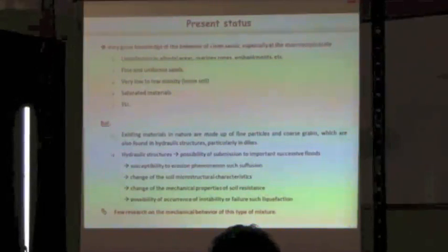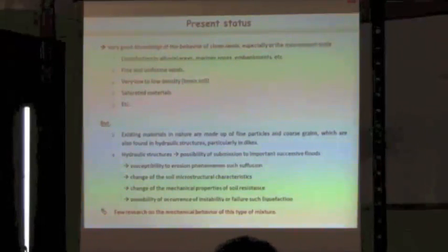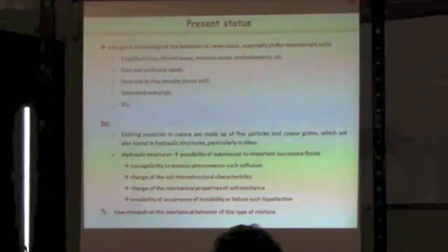particularly in dikes. Why did I introduce hydraulic structures? It is because such structures are often submitted to important successive floods, which could wash out the fine particles from the soil by water flow, leaving behind a coarse grain skeleton, which could become loose.